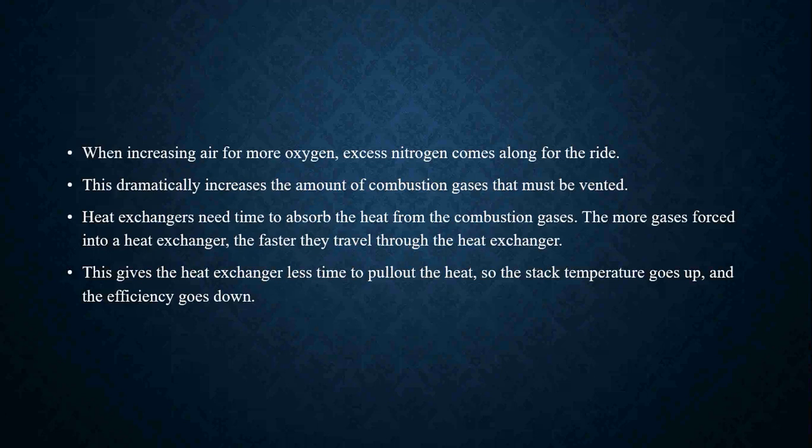Your heat exchangers need time to absorb the heat from the combustion gases. The more gas is forced into a heat exchanger, the faster they're going to travel through the heat exchanger. That is where our efficiency really is taking place, is how fast or how slow your combustion gases are making their way through the combustion chamber or heat exchanger.